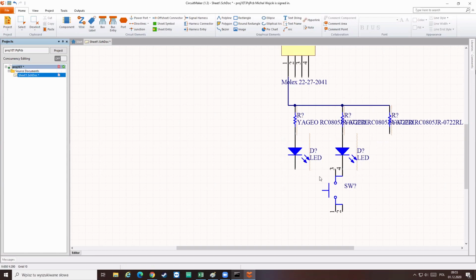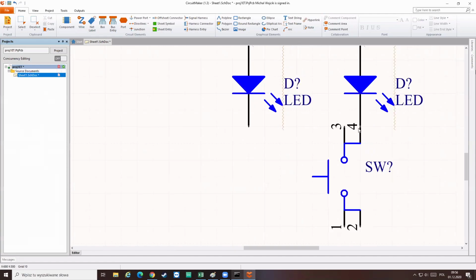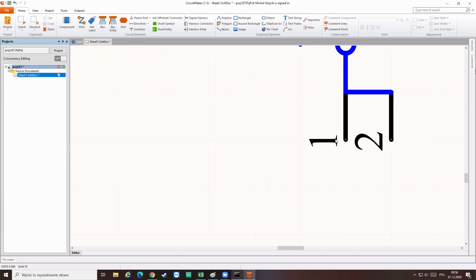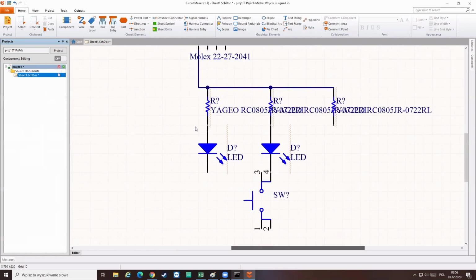Important thing is that sometimes you may not know, for example in the case of a tactile switch, where it starts from. Should I start the line from here? No, you shouldn't. It will not really be connected. Each element has a tip. If you zoom in, you can clearly see those little points in here, those are tips, and you should always connect from tip to tip. Otherwise it just will not work.